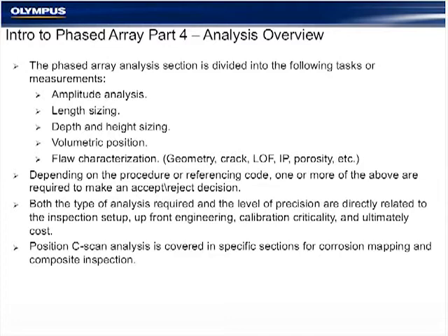In fact, as a service technician working with customers, the overwhelming majority of data I see typically has more mechanical acquisition problems than software or calibration problems, meaning the probes were not adjusted well, the mechanical carbides on the feet were not positioned well, or some of the scanner mechanics may have been loose.